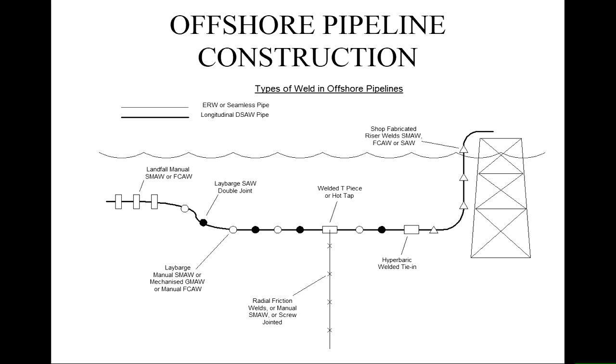And the pressure has a big effect on manual welding. The length of time that a welder can operate to high quality is very short under these hyperbaric conditions. So we try to make more use of automated processes where possible under those circumstances. So we don't want to have to do things with divers and welders if we can avoid it.